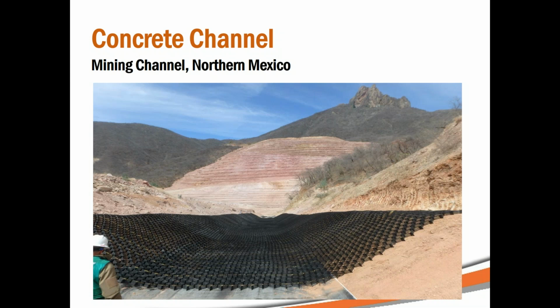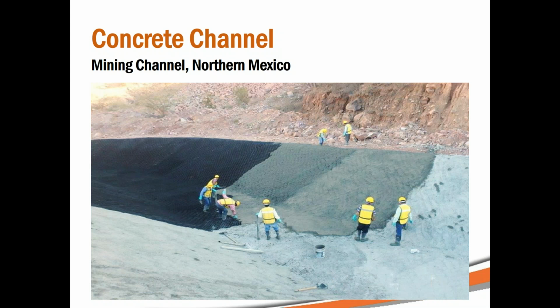Because the GEOWEB panels are the formwork and reinforcement, it vastly decreases the amount of installation work and cost of materials. The concrete is poured direct and is usually hand leveled to the top of the cell. This way, all of the concrete is confined and protected, and you can guarantee that the channel will have a consistent concrete depth. Concrete can be poured into sections like you see here, without losing strength or having seams.